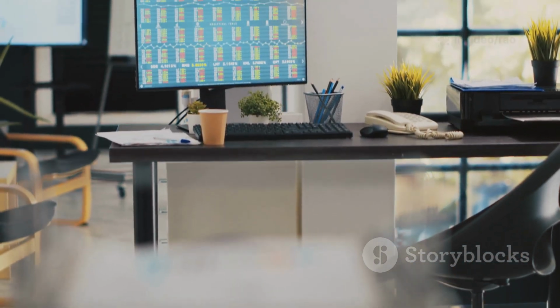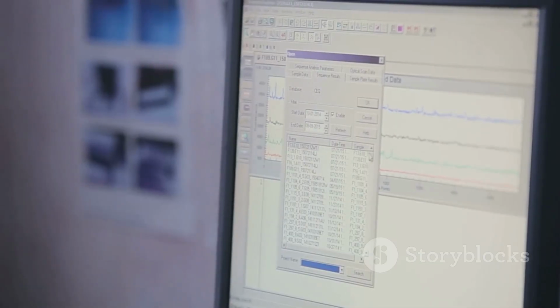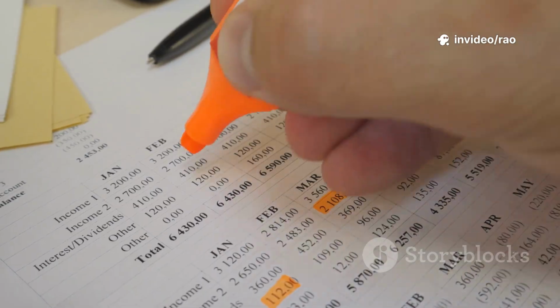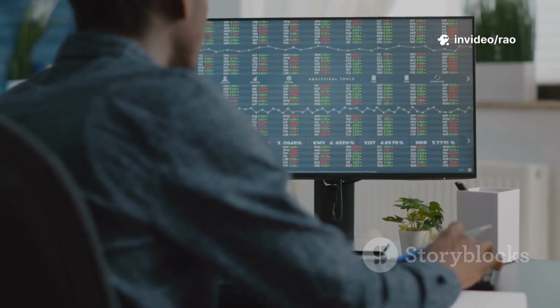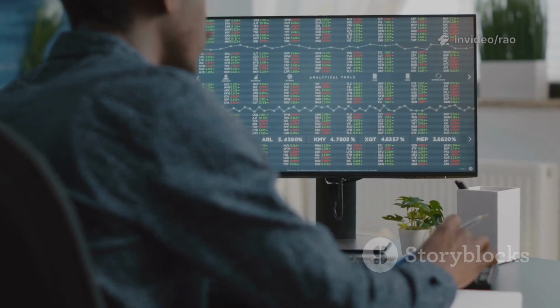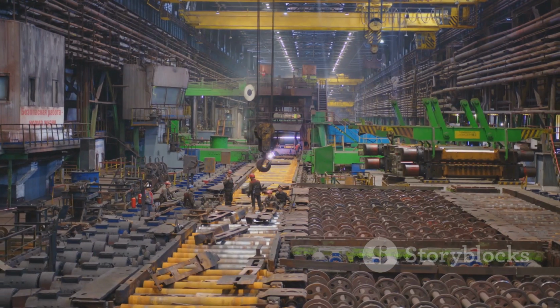A1, slab length, M. B1, 4. A2, slab width, M. B2, 3. A3, bar dia, mm. B3, 12. A4, spacing, mm. B4, 150. A5, hook factor, B5, 10. This lets any slab be calculated by changing those 5 values. Next, calculation section with formulas.